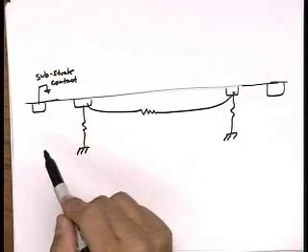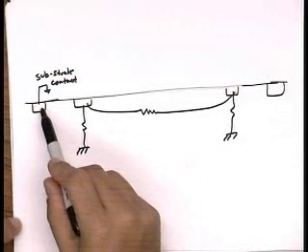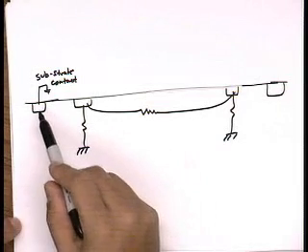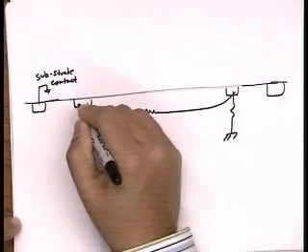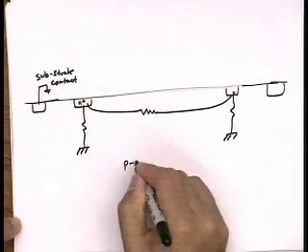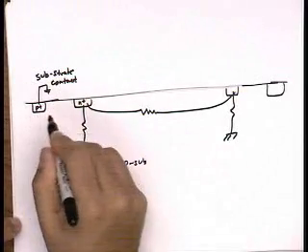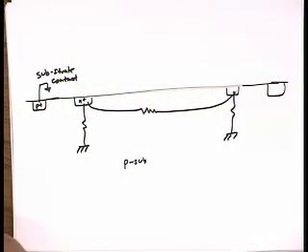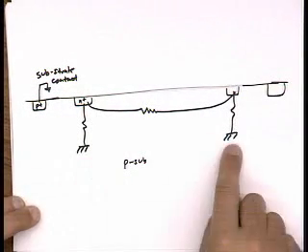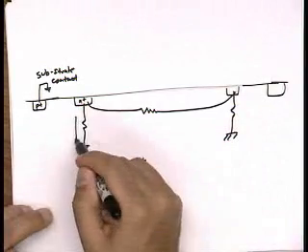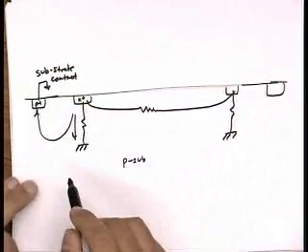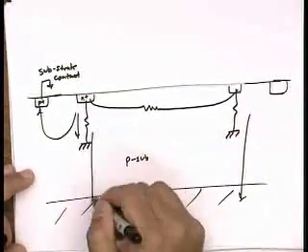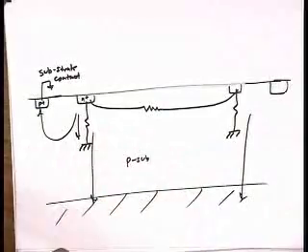For instance, if I have an NMOS device, I'm going to put a substrate contact right near it in order to make sure that it's grounded. So if this were, let's say, an N plus region, and this is a P substrate, I put a P plus here to make sure that the body of the transistor has a well-defined potential. So this current here going to ground can either be the current going to the surface, or if we actually do contact the backside of the substrate, it's the ground current. Of course, in general, it's both.